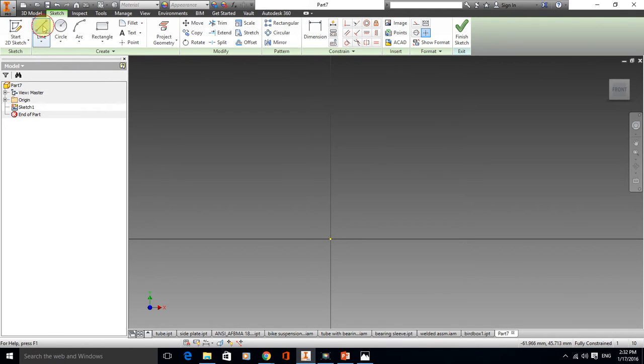Now let's just select line. If I drag my cursor over my crosshairs, you can see it changes to green, and it automatically selects X0, Y0. Okay, so it's snapped to the 0 coordinate. Let's drag my line across. Now it's snapped to the horizontal, and if you look just below the right hand side of my cursor, you can see a horizontal constraint that has been applied.